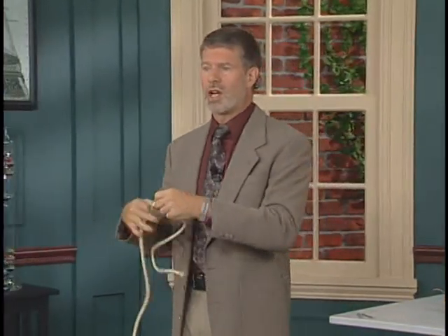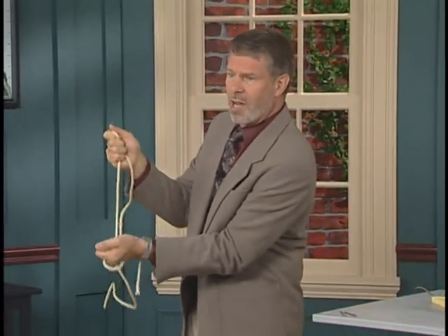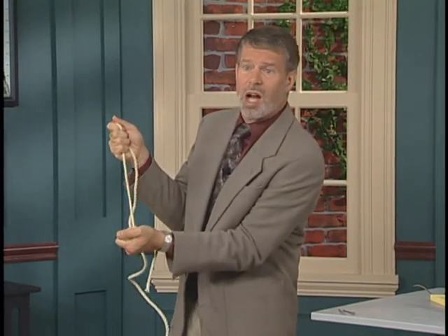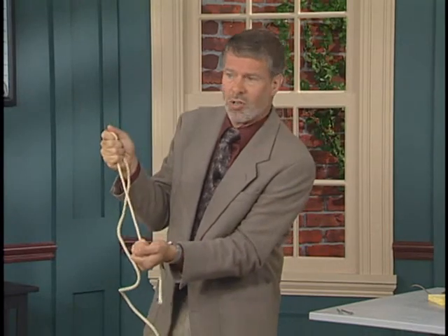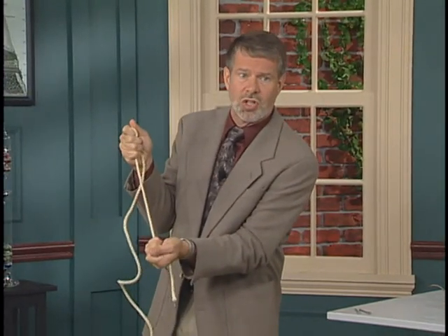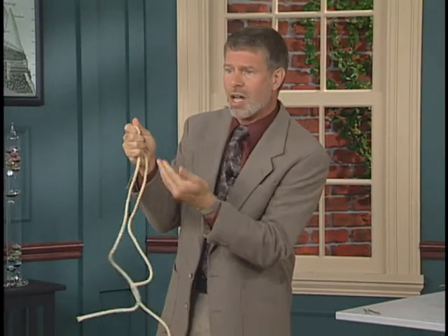And a real common example is just a nylon rope. This is an ordinary nylon rope. It's made of synthetic polymer fibers. There's strong bonds in one direction, and this fact leads to the biggest danger of this kind of rope, the fact there's only bonds in one direction. You see, even a few damaged bonds can destroy a nylon rope. Think about that. You see, just break each polymer strand in 1 or 2 places, and the whole rope is drastically weakened, even though it may look fine.